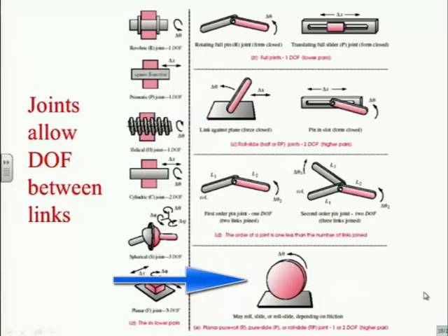This is a unique kind of joint. It's a wheel on a surface. And this is sort of schizophrenic. It doesn't know what to be. It could be a full joint, provided that I don't allow the wheel to slip. Imagine it's your bicycle tire or your car tire, both of which are made of rubber, which has a high coefficient of friction. And you're typically riding on a surface made of macadam, or concrete, which also has a high coefficient of friction. And so as I pedal my bicycle, I don't tend to slip the wheel, and I have 1 degree of freedom between the 2. So the wheel rolls on the surface, and the degree of freedom is the theta of the wheel. Wheel's turning. Huh? Make sense?